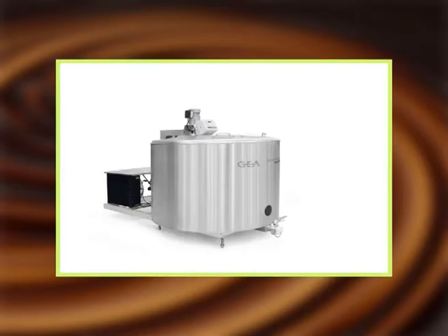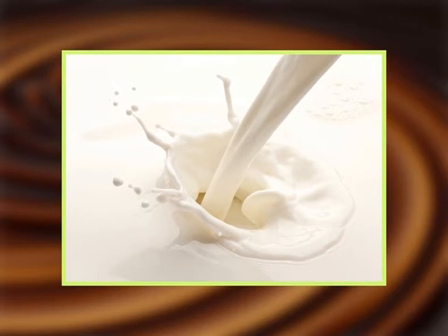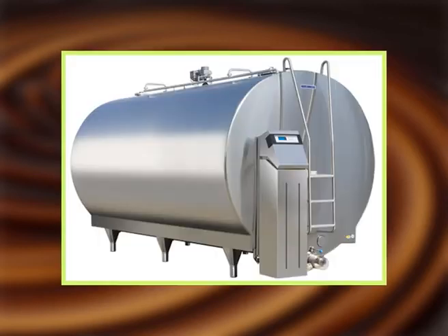Aging is performed in insulated or refrigerated storage tanks, silos, etc. Mix temperature should be maintained as low as possible without freezing, at or below 5 degrees Celsius. An aging time of overnight is likely to give best results under average plant conditions. A green or unaged mix is usually quickly detected at the freezer.